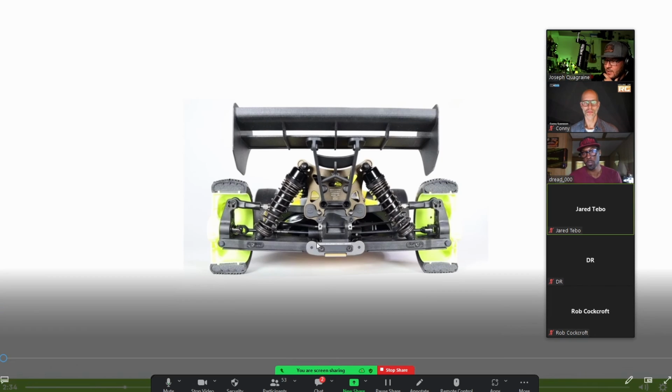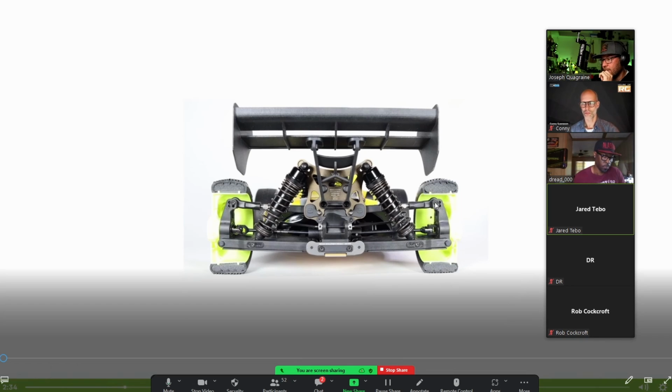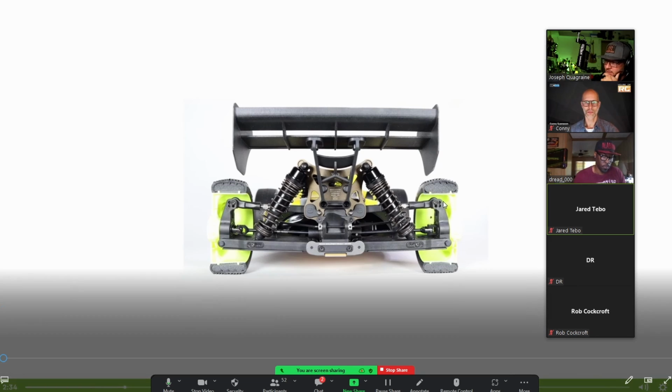So this is the first area that I would think about changing on a track. And like I said, I think about this in terms of support. Either I need more or less. That's what I do with the height of the arm. I would say that the second thing would be the length of the link on the hub, front and rear. I tend to match front and rear to not have a big difference in the lengths of the links.